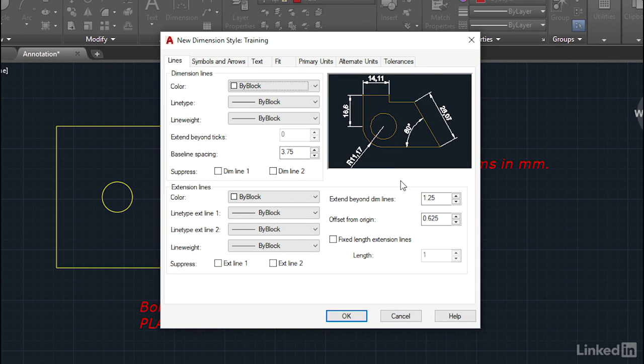Now, as soon as I do that, it opens up this great big complex dialog box. Make sure that when you are placing your dimensions, all of your settings are set to by layer. Then it adopts the properties of the layer that you are using for your dimensions. Now, if you just look past the dimension style dialog box, you can see that I've left the current layer on text. Don't worry about that. It's not a problem. As long as you make sure that you place your dimensions on the dimensions layer in the drawing later when we place the dimensions, you'll be fine.